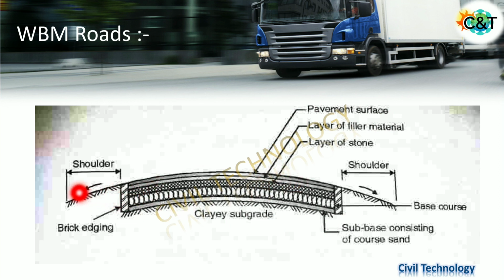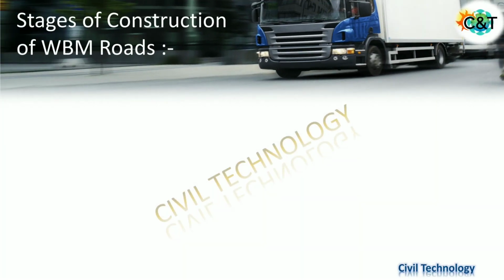Here you can also see the shoulders and bridge edging. This is the lateral confinement. Yes, this bridge edging you can see, this is the lateral confinement. So this is the general profile of the WBM road. So the first step is the preparation of subgrade.